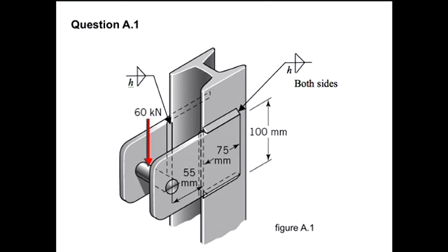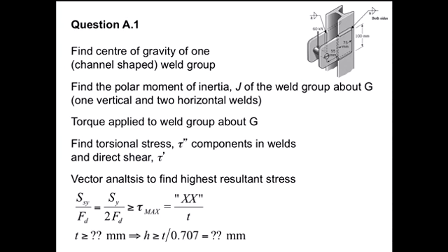Hopefully there's a cantilevered load applied to the pin. It's going to try and twist, so it's got a moment applied. It's also got the direct shear associated with that force. So there's some stuff to be done. It's not totally symmetric in terms of the weldment appearance. It's a C shape, so you've got to locate the centroid or centre of gravity, G, for the weld group.